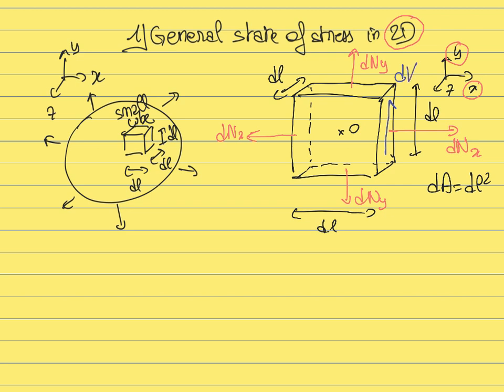because it's a shear force, not a normal force. So this force is applied along the surface, not orthogonal to the surface. And in this case, we are going to define the direction of this force using two indexes. First, we are going to say that this force is applied on the x surface. And then we are going to say that this force is along the y direction. So this is how we are going to refer to shear forces.